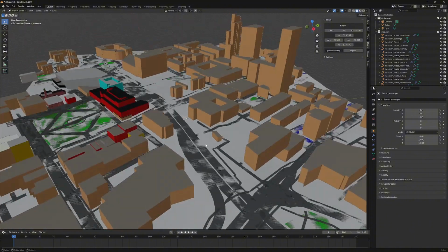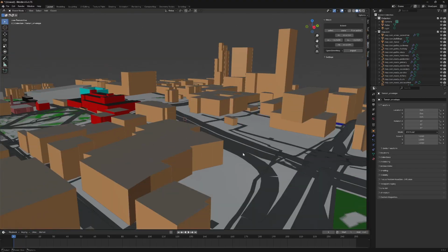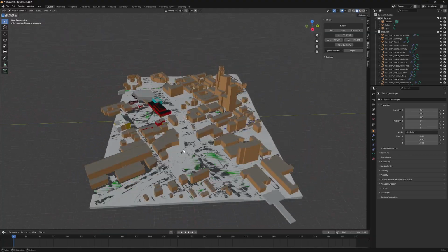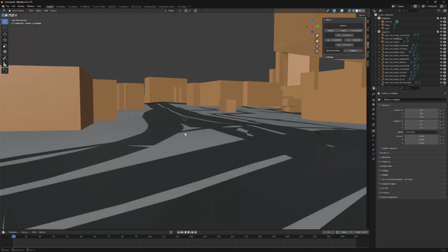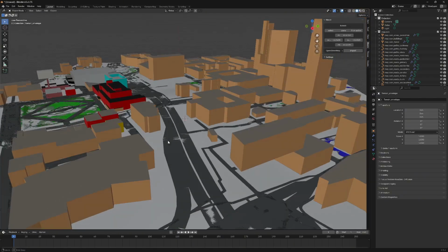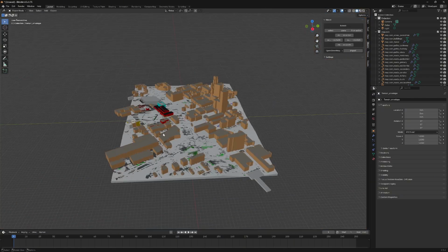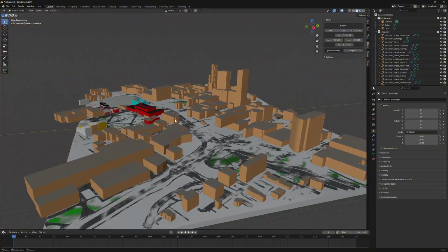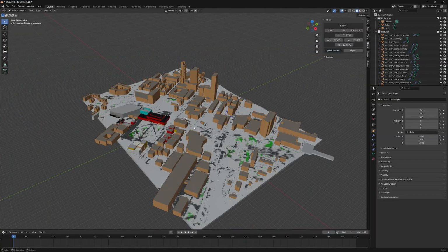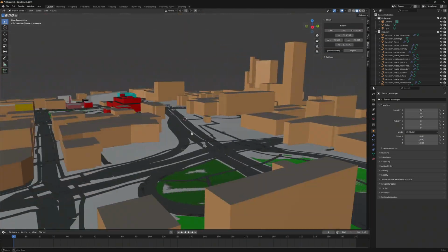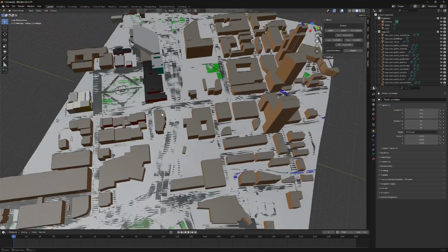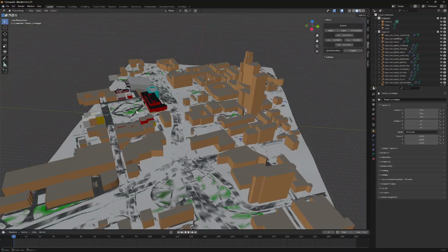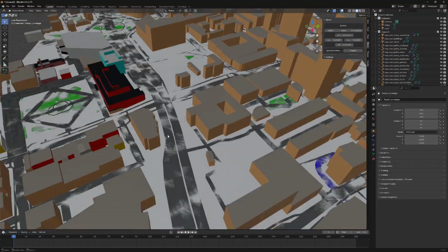But what you'll see happen here is that the road is constrained to the terrain. And all that's happening here is that the faces are just intersecting one another because they're in exactly the same place. And so, if you don't like that, or if you want to change that, what we would do is just make sure that we don't generate the terrain first, and then we'll create just a flat set of roads instead of having these project themselves onto our terrain.